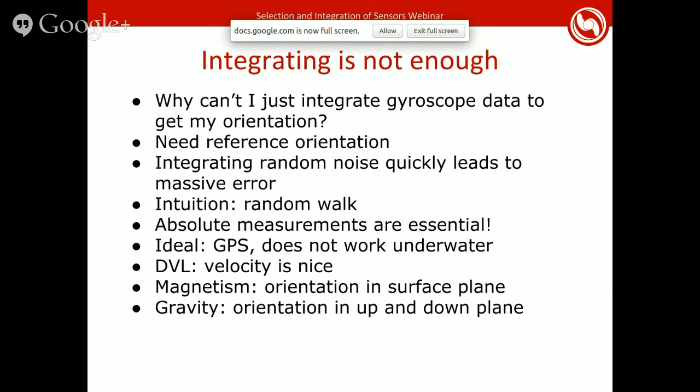You're still at the same state, so you might as well be 1 away from your desired value. And in fact, there's a theorem that says in one-dimensional random walks, every single integer is crossed an infinite number of times given enough time. So that kind of gives you an intuition as to why these things can quickly diverge. And that also assumes perfect integration, which is impossible in practice because you have a discrete sampling of the signal.